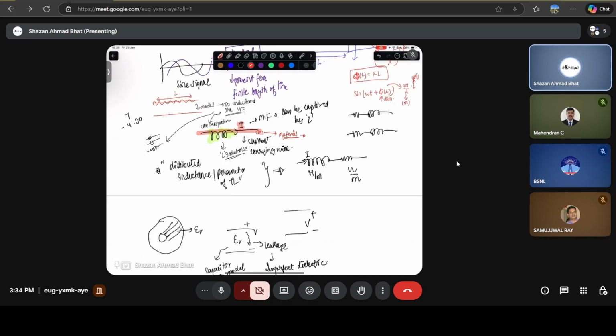This loss can, by the way, tend to zero if you design it in a certain way. Let's say, for example, you have superconductors, then this R can tend to zero, but the inductance and the capacitance are always going to be there, because these are parameters which are always going to remain there, no matter what, even if you can make the resistances go to zero, because these are associated with the motion of the electrons, motion of the currents inside the wire.